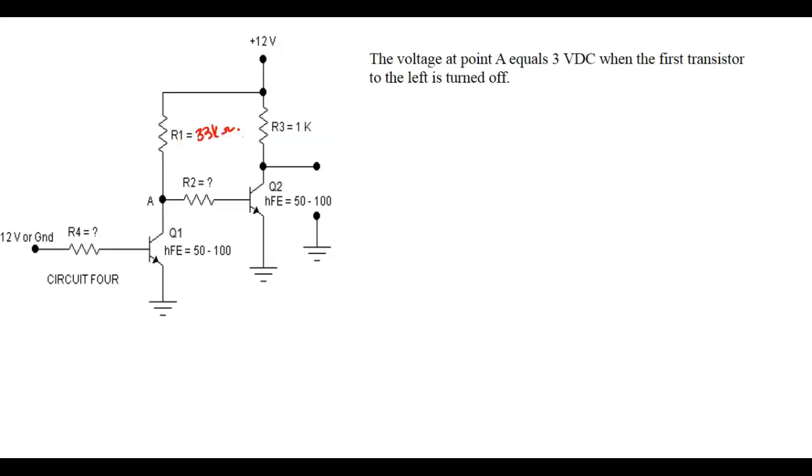Okay, so now we don't have to choose anything for R2, R1, or Q1 because we calculated that. Over here I'm going to put 12 volts, so this guy right here is going to drop 11.3. When Q1 turns on, R1, instead of dropping 9 volts, is going to drop 12 volts. Y'all understand that? What we just did is turn this guy on, which means that point goes to approximately 0 volts. This guy right here turns off. It has no base current.